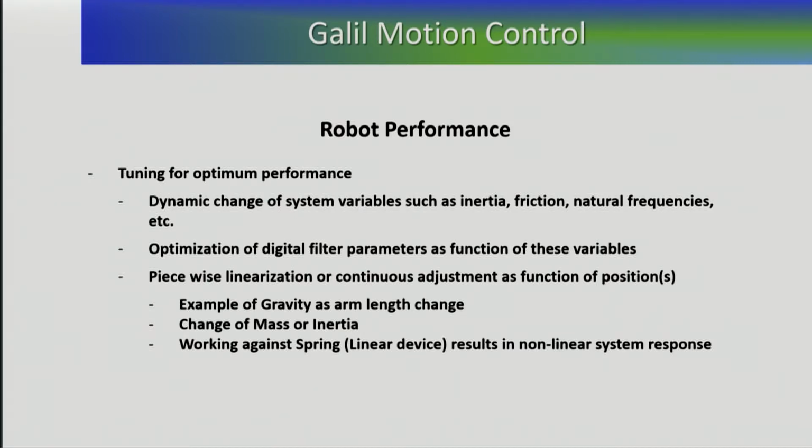That means you have to continuously compensate for the spring, and you can define that as a function of your position. So compensation for the spring can also be applied into your digital filter that allows you to correct for that additional nonlinear component. So we talked about gravity, mass and change of mass or inertia, spring devices.